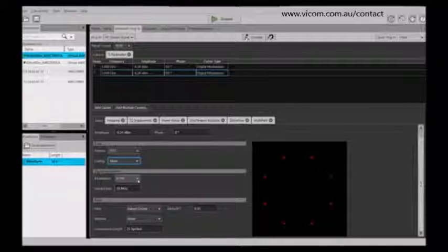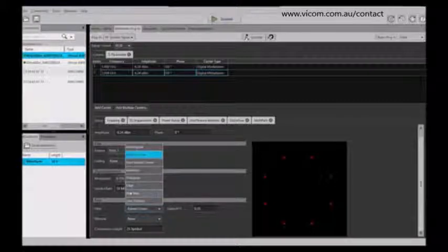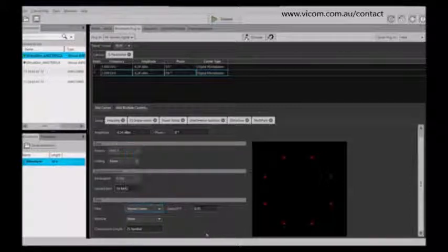So you can also pick, of course, your symbol rate, and this would be for each waveform that you've got selected. So right now I'm working on this particular waveform. If I change the frequency here, it would be shown highlighted up above in the actual index of waveforms. You can specify your filters. Again, you have quite a variety of filters that can be used for your modulation, and also your alpha values can be selected here.